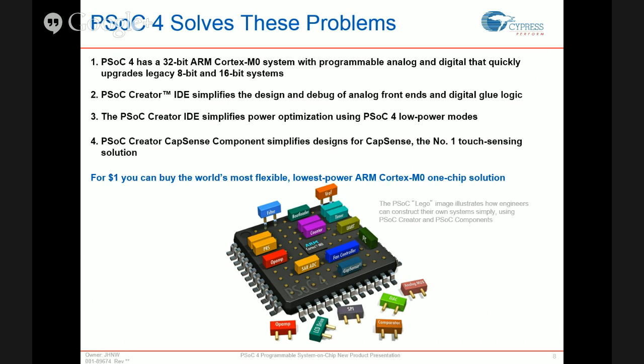We also offer a lot of flexible power modes with PSoC, 5 of them to be exact, and in these different power modes, various analog or digital peripherals are either available or in sleep, so you get to optimize your system for just the right amount of power consumption. PSoC Creator also simplifies power optimization by providing you very easy-to-use APIs to switch between all of these various power modes. And then the whole concept with PSoC Creator is really to simplify embedded system design, and we'll show you how we do this today with a quick hands-on demo.